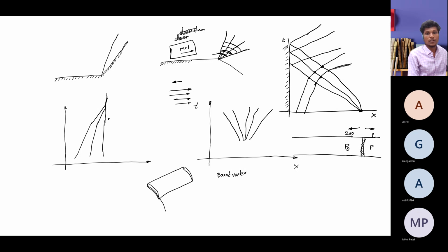For a finite wing, the hint was also given, but I did not see it clearly. I was reading only the question, and I later realized that they're asking only for the wing. They don't want to model the trailing vortices or the velocity in the wake. So the good approximation, how you can approximate this lifting line for a finite wing, is to first model the bound vortex.